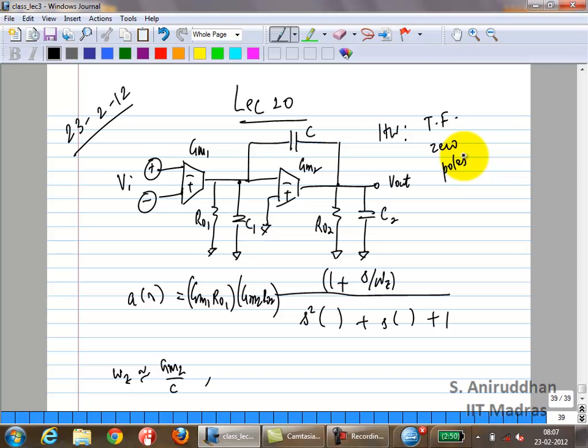The gain of the stage is approximately GM2 RO2, so it's going to look like that times C, plus C1. That is going to be the capacitance associated with the pole. The resistance is just going to be RO1, right? Similarly, at the output, what do you get? C2 plus C times RO2, right? So those are the approximate positions.